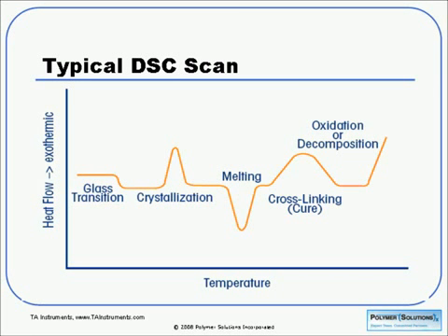But I do want to point out here that the results that we usually get from these techniques are heating rate dependent. So if you're comparing your data to someone else's, you want to make sure that they were done under the same conditions. But you can see that DSC gives us lots of information, so it is one of our real workhorses in our lab.